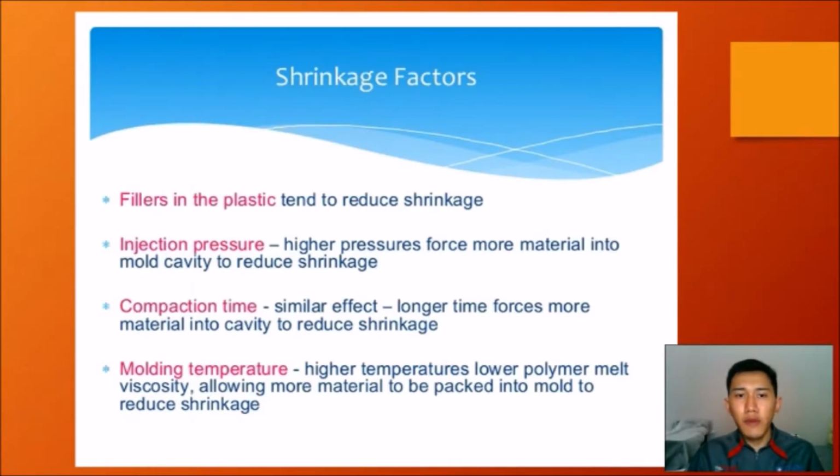There are several factors that affect the shrinkage. First, fillers in plastics tend to reduce shrinkage. The second one, injection pressure. The higher the pressure, the more material is forced into the cavity, which reduces shrinkage. The third factor is compaction time. Similar effect, a long time forces more material into the cavity to reduce shrinkage.